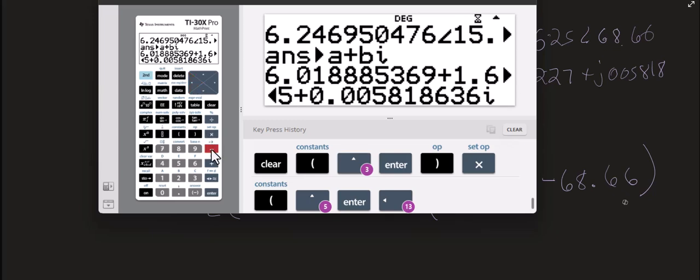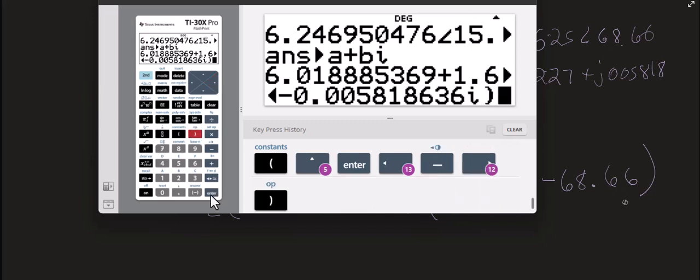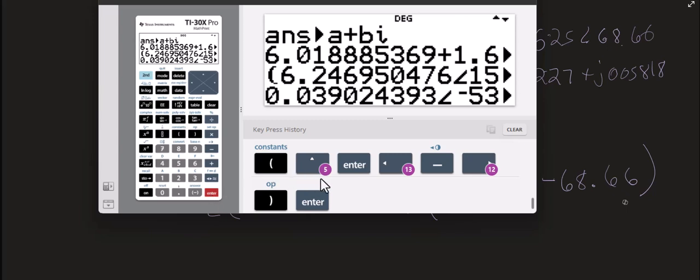Would you say each time we're given a circuit, we can safely assume it's a sinusoid if it's an AC circuit? Oh, I mean AC, I'm sorry. Yeah, that's why we're able to take advantage that V RMS, for example, equals the amplitude of V divided by square root of 2. Exactly. Okay, just making sure.